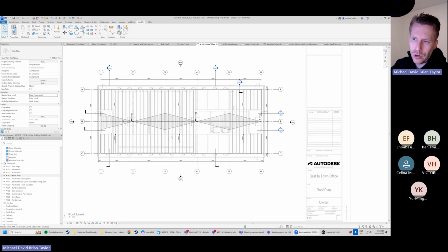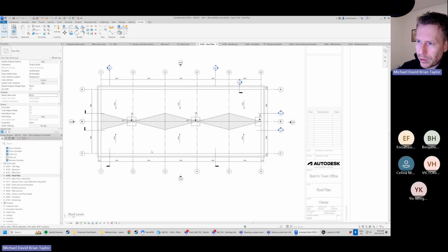And that's great when you're trying to draw the roof for sure. Super helpful to see where the edge of our walls are, so we can get our roof in there properly. But when it comes to drawing legibility, really all we want to see are the roof slopes, the roof, and the parapets. So a simple way to eliminate that, we're just going to drop this down and hit none. Just cleans your drawing up a little bit.